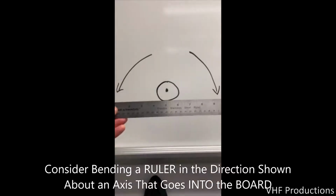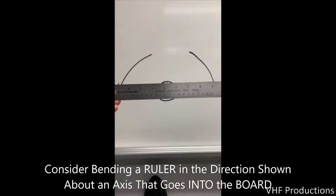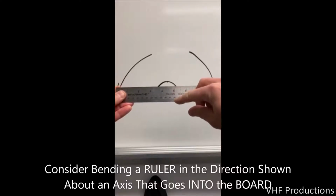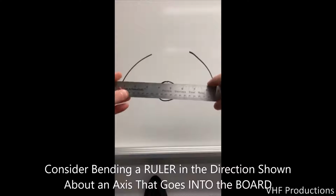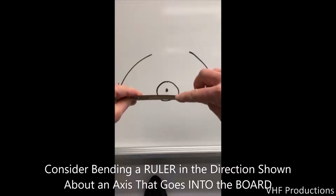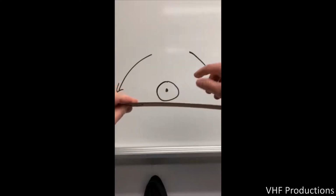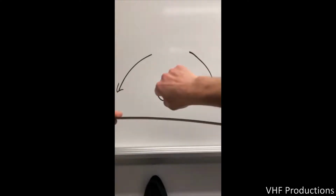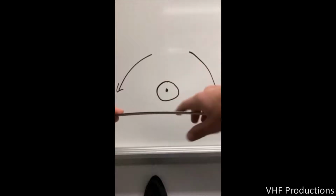As a simple demonstration of the concept of how geometry and the orientation of a beam to the loading direction affects the stiffness that the component can provide, we're going to demonstrate it with a thin metal ruler. The geometry of the cross-section of the ruler is a very thin rectangle. It's a ruler about 12 inches long, but the cross-section is approximately 1¼ inches tall by about 1/16 of an inch thick.